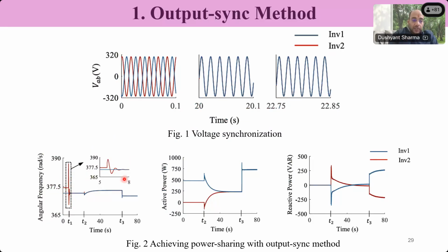So here, as you can see from this, the frequency will start to match, and the frequencies match completely. At that point, we turn on the circuit breaker. If we turn on the circuit breaker after absolutely proper synchronization, there will not be any transient in the system. There will not be any power flow. This P will be absolutely 0.